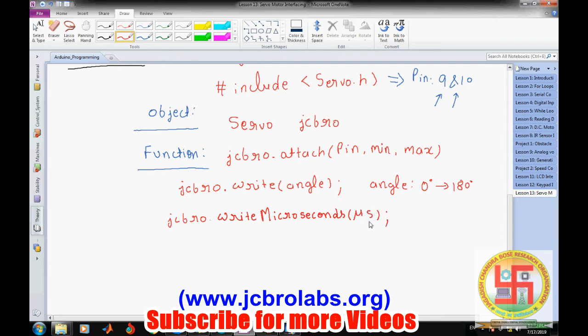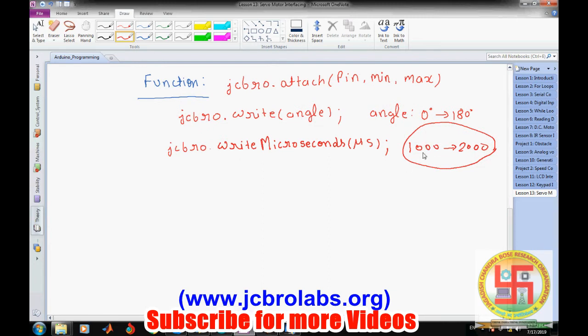Okay, so it has to be in the range of 1000 to 2000. Microseconds means 1 millisecond to 2 milliseconds. Within this range, the servo motor will rotate from 0 degree to 180 degree. Once again, this value is for general motors. Suppose you are using a specific servo motor with its own requirement, then you can change these microseconds from like 750 to 2500 depending on the kind of servo motor.